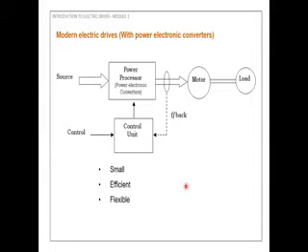For example, the actual speed of the motor is 1400 RPM. The standard speed is 1500 RPM. So there is a 100 RPM lag between standard and actual. So the control unit generates a control signal to improve the voltage of the power semiconducting devices inside the rectifier unit. That means the power electronic converter.